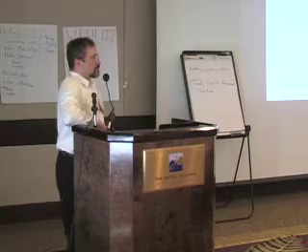That overload typically is 10 minutes out of an hour, so we're doing hour intervals. Maximum overload, if your generator has an overload rating, is 10 minutes for a diesel generator. And for inverters, you have multiple surge. You can do bigger surges for shorter periods of time and smaller surges for larger amounts of time.